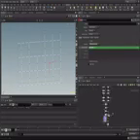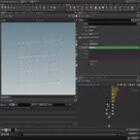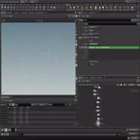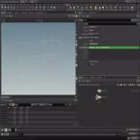So let's set it to expression. And let's delete everything from the perimeter which is longer than, and that is depending on our null node over here. So let's copy this value, copy this in there, and let's multiply it by 1.5, so it's always in between 1 and 2 sizes of itself. And there we go. So here you can see we've deleted that primitive. And now we don't have any primitives anymore which go into the wrong direction.